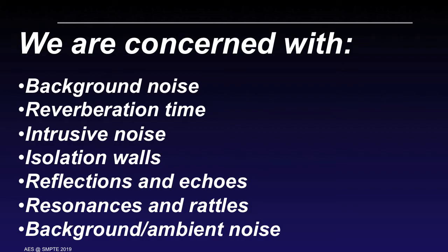We are concerned with background noise, as I mentioned, which is needed for wide dynamic soundtracks. The reverberation time: we don't want the room to add its own signature to the sound. Intrusive noise: we don't want to hear things happening in the lobby or the cinema next door. We worry about the walls to ensure that doesn't happen. Reflections and echoes in the room should be minimized, if not totally eliminated as much as possible. Resonance and rattles in the construction of the building.